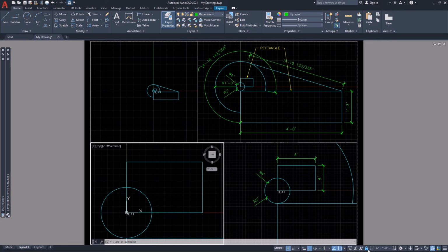Glance down at the annotation scale displayed in the Drawing Aids toolbar to verify that the scale was not errantly changed from 6" equals 1 foot scale. If this scale factor does not display, the user will need to unlock the viewport, reset the scale factor, and then relock the viewport. Left-click one time in the lower right viewport to switch the active viewport window.